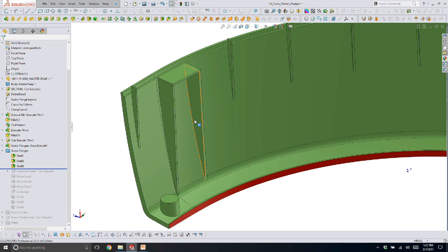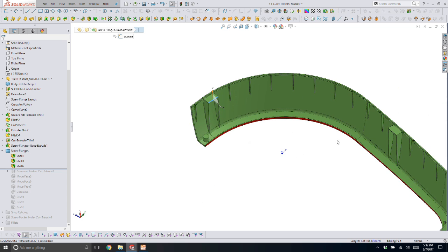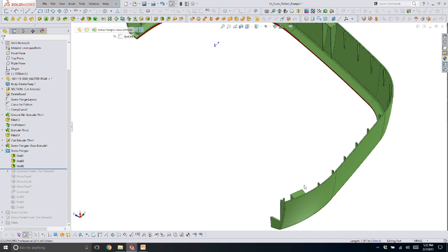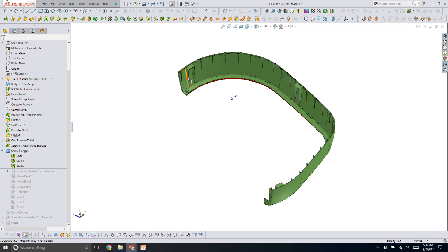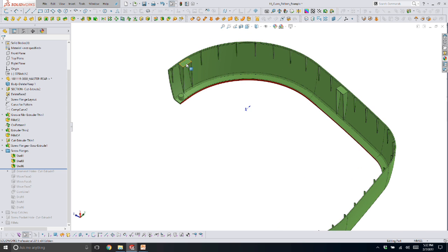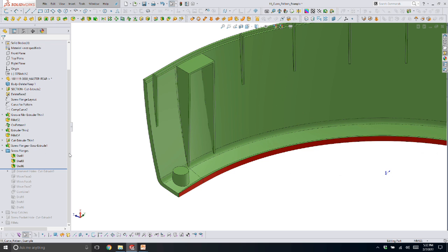If I had created this in another way, I would have needed to set up maybe a reference sketch to get this angle because it's not vertical. Then I would need to set up a sketch here, and a plane here, and then 1 sketch, 2 sketch, 3 sketch, 3 extrudes. So just be thinking of how much you can get with a shell when modeling mounting details and such in your part. Here I'm getting all of this extra geometry by using the shell to remove it. The only downside is that you can only shell 1 body at a time, so I have 3 shell features.